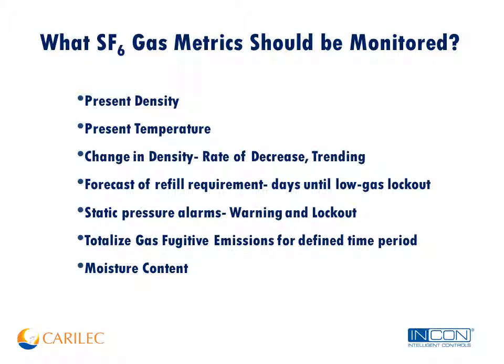In the future, it will become more important to measure the moisture content of the gas. As we said before, moisture in a circuit breaker is bad news from many standpoints, but primarily that it mixes with the gas byproducts and creates a very caustic atmosphere for the moving parts. So as moisture sensor technology improves, we can easily add it to the optimizer and have it be an alarmable feature.